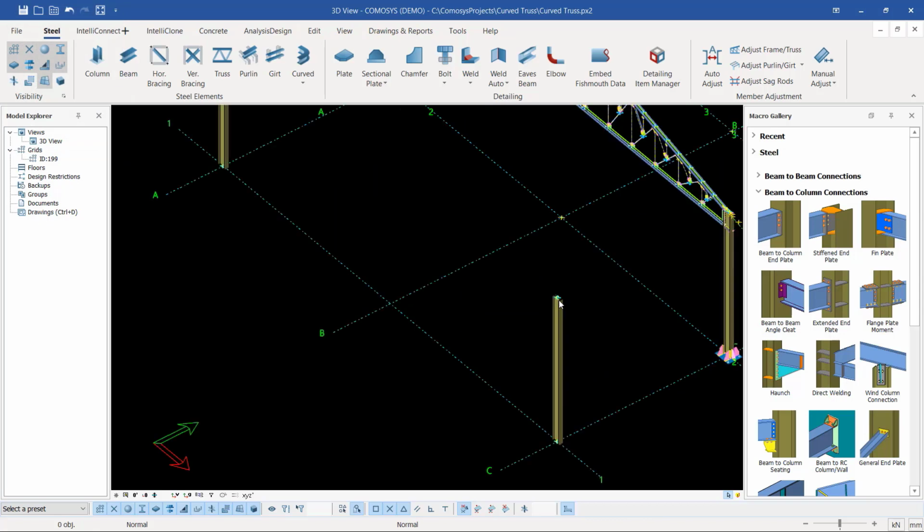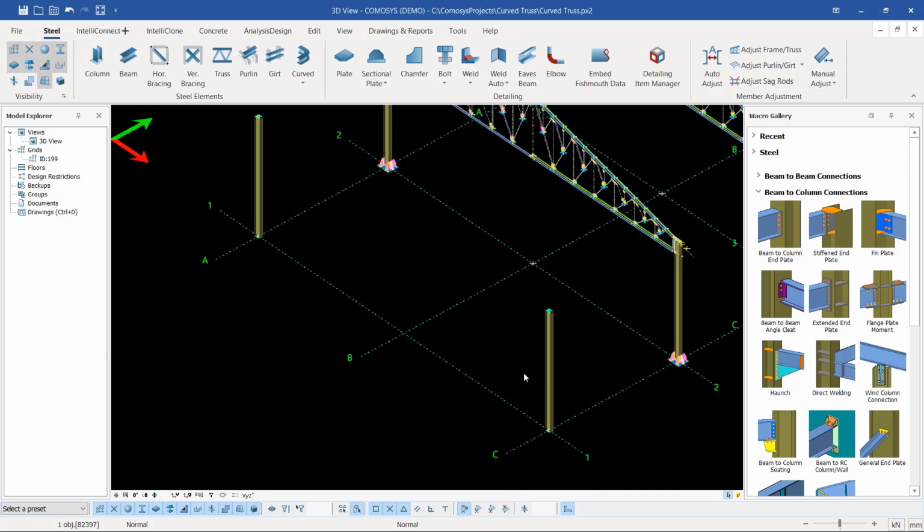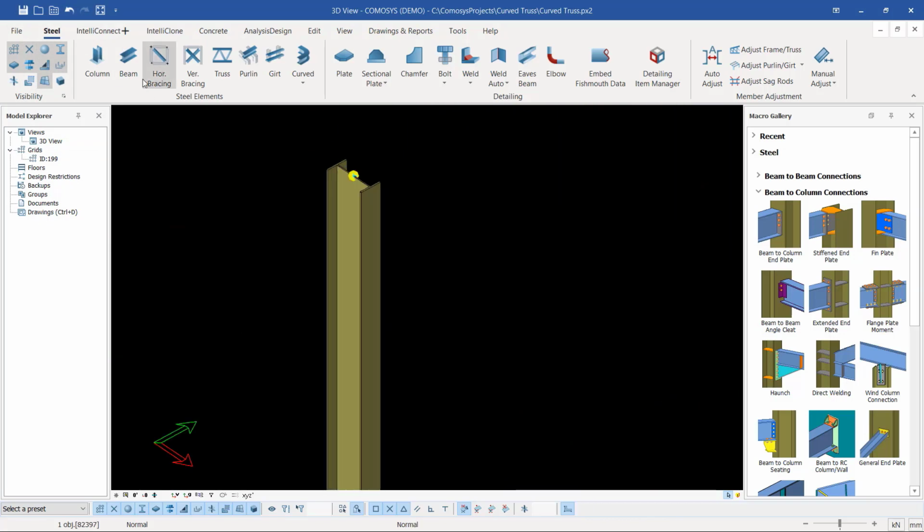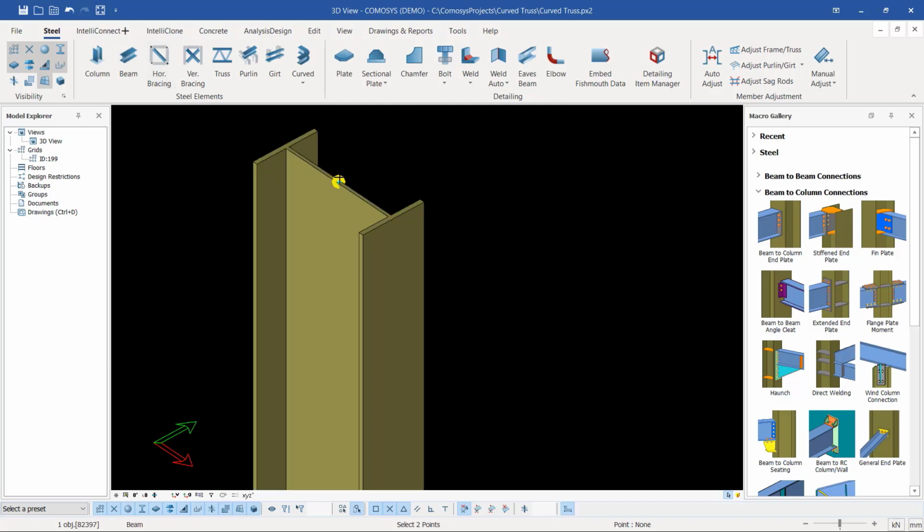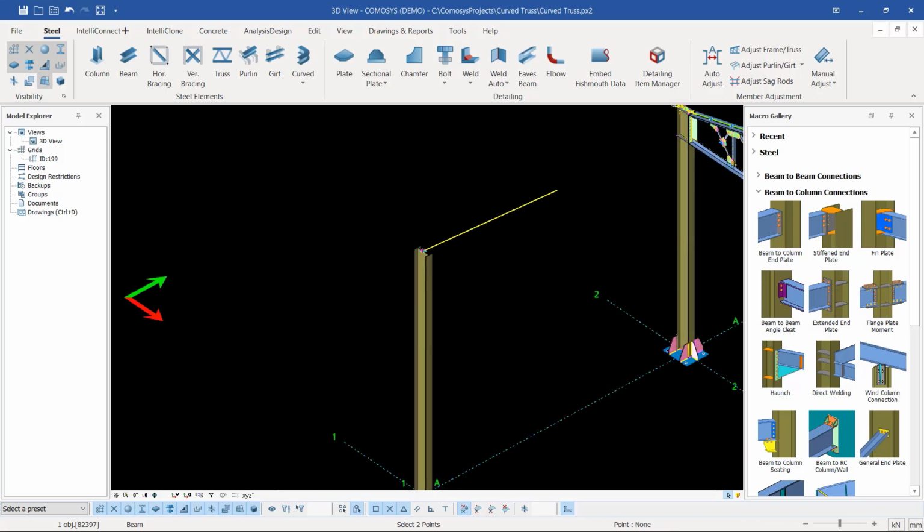So the next step, I'm going to create a rafter. So to create a rafter is easy. We just come to beam here and snap on top of this joint here, snap on it, then move your cursor slightly upward, and we want to place a rafter. So press Control Alt. The moment you place your cursor upward here, just enter, then press Control Alt, then type,